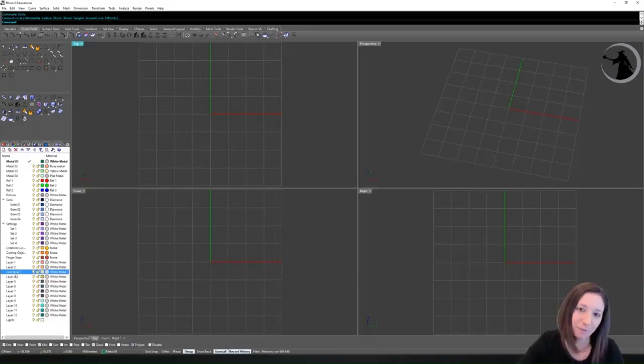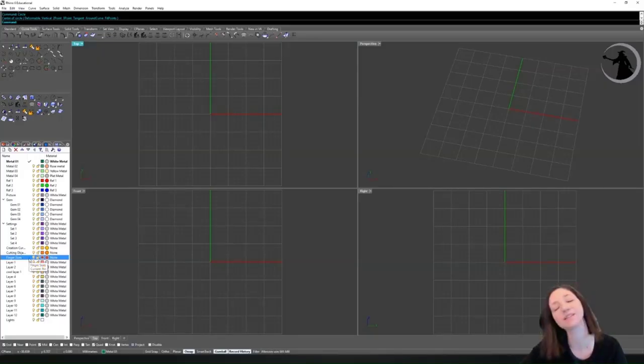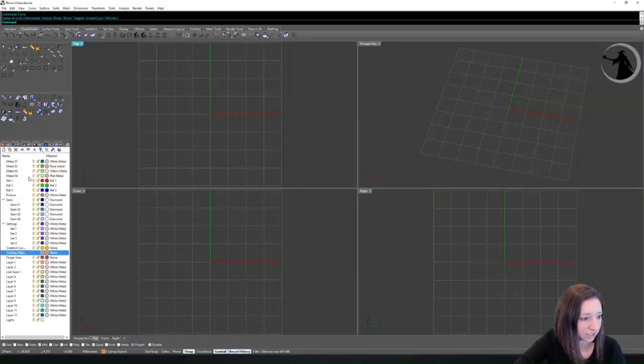So as you become more accustomed to CAD modeling, I suggest you really think about how you want your layers laid out and name them different things. Something to note about layers: if you just click on this and have it highlighted blue, that is not the active layer. It's just the layer that you have clicked on. If you want it to be the active layer, you need to make sure that little check mark has moved down to that layer. There's this little section here where you'll see there's always one check mark. If you click in that little section, it will move that check mark.